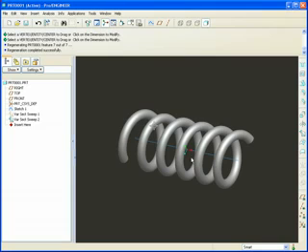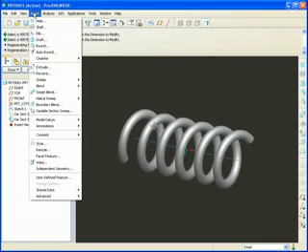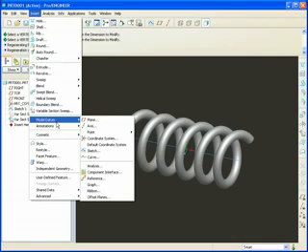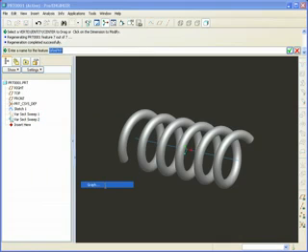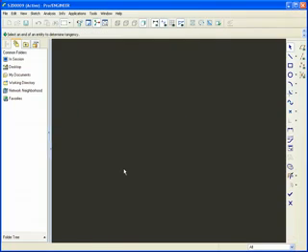Well, this is really cool. Take a look at this. If I go Insert now, a model datum that's a graph, and I'll give it a name, maybe we'll call it turns. Now the idea here is that ProEngineer is asking me to create a graph that I'm going to use to control the turns.